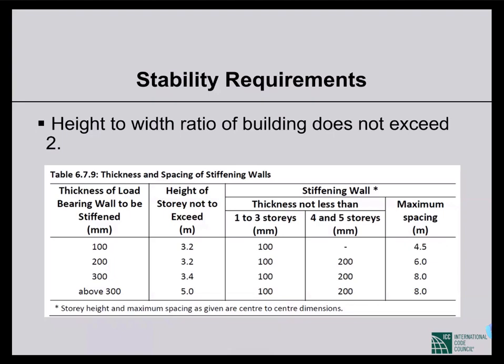If we would like to design a 2-story DRM structure, what load combination should we apply? Just for working stress design, follow part 6 chapter 2 load combination for working stress design. And if you design the shear wall or slender walls, then follow the strength design load combinations of part 6 chapter 2. This is the same for concrete, for steel, and for masonry. There's no difference. Is any provision given in BNBC 2020 for earthen building? No.